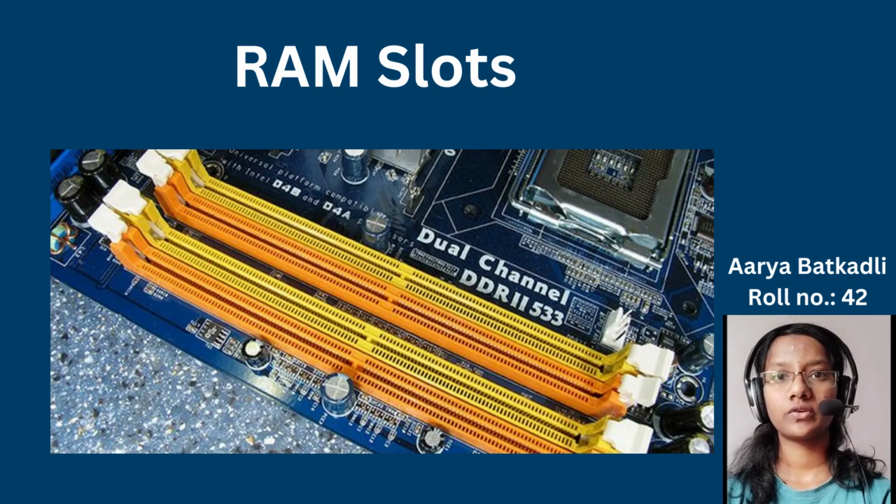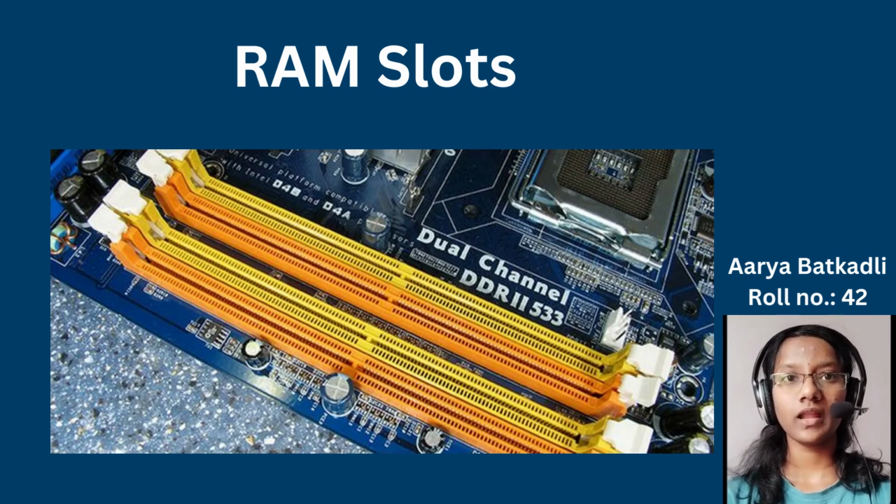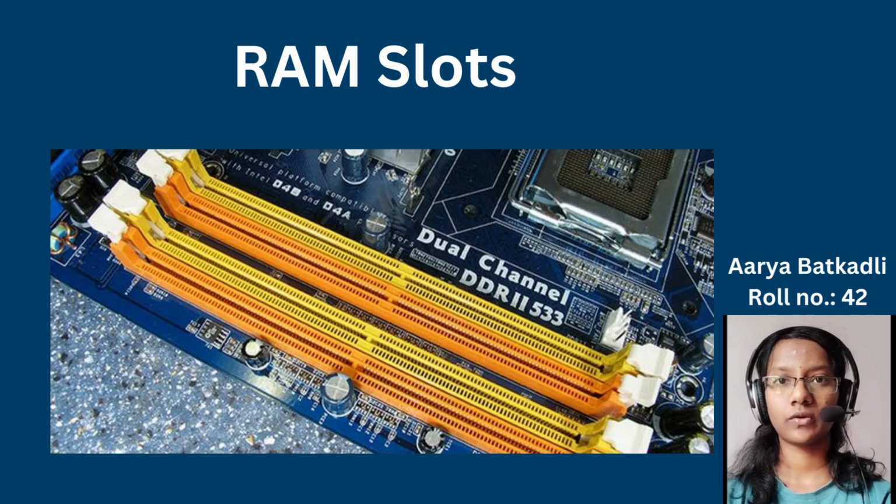Motherboards are designed to support specific memory types, and the RAM slots are configured accordingly. It is important to verify the supported memory types and maximum speed specifications of the motherboard to ensure compatibility with the RAM modules you intend to install.